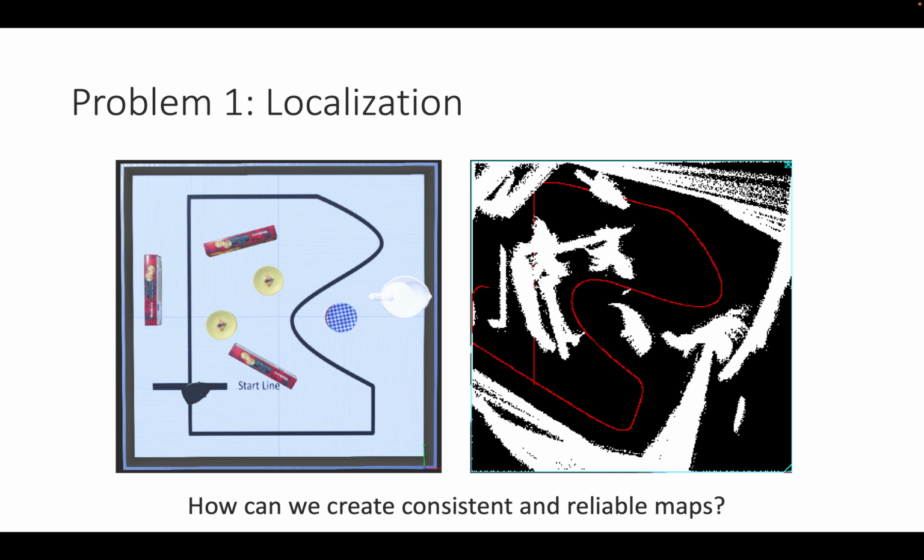So the first problem with the map is localization. Here I have been running the map using just the robot odometry. You see it started driving straight up, and then when it did its right turn, I misjudged the angle by a few degrees, which led to a tremendous error in my mapping performance. I have this wall here all over the place, and it keeps shifting as the robot starts increasing its error. Now it gets worse and worse, and the map gets completely useless.